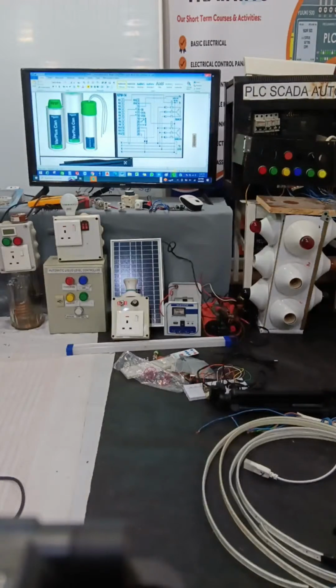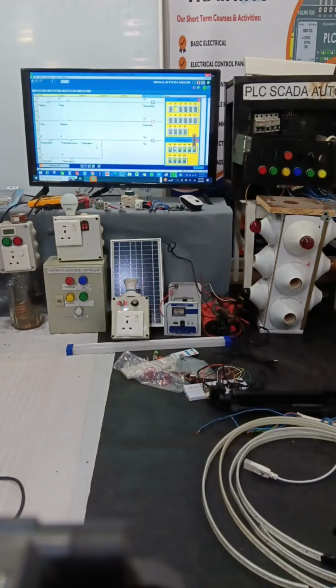So now in our system, we will consider this as auto mode. Suppose the signal came to switch on one 10 kVA contactor, so this will close. Now you see this 10 kVA capacitor is on. Now suppose the demand requires an additional 15 kVA. So the second contactor will close from the controller. Now one 15 kVA capacitor is on. Now it's 25, 10 plus 15.